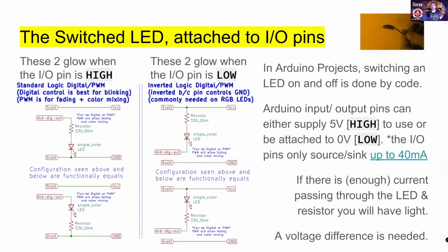And how you have it attached, and the drivers: if you have certain types of transistors, some prefer certain types, if you're using a transistor to drive them. So there are different contexts where you may need to use one or the other. Like an N-type transistor might like the right-hand version a little bit better. So is that still a true diode, where with that LED it's flowing from the cathode? Mm-hmm. Yep, it's a power trick, but it's totally a diode working in the right direction.